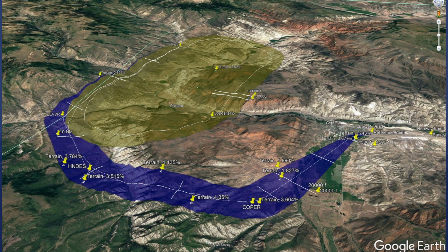And in the 2000s, the FAA came out with AC 120-91A to define recommended guidelines on how to develop engine out procedures. So we follow those. We develop this path here, and all the obstacles that are inside that blue corridor are included in the engine out departure procedure and are considered during the runway analysis.